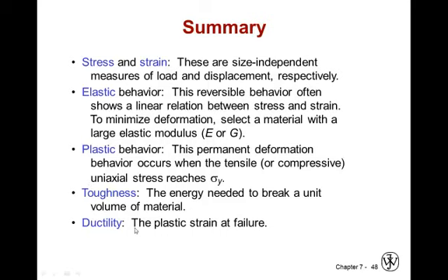Ductility is the opposite of brittleness. Ductility is the ability of a material to strain for a long period of time. So the plastic strain at failure is the measure of ductility. If you have very small strain, you have very small ductility. If you have a very large strain, you have a high ductility. We also subtract the elastic strain to calculate the actual percent elongation. The sample problems shown here are gone into greater detail and are posted on the same site as this is.